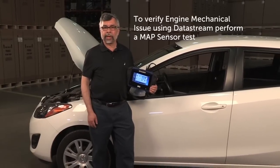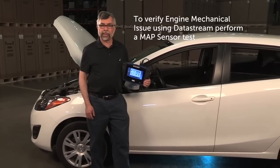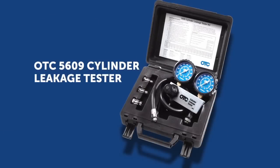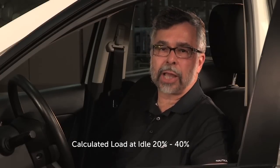To do a quick verification of an engine mechanical issue using the Encore, perform the following test of the MAF sensor. Testing the MAF sensor will help verify that you have an engine mechanical issue. Key on engine run at idle and at operating temperature, the MAF sensor should read 1.4 to 1.6 volts. A second method of verification is to use a vacuum gauge, compressions tester, or cylinder leakage tester. If the vehicle does not have a MAF sensor, go to Global 2 and use calculated load. It will give you the exact same results.